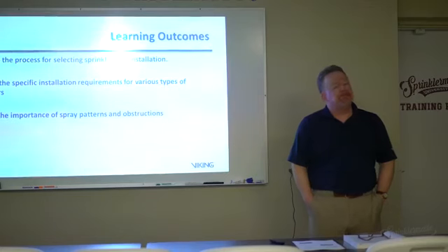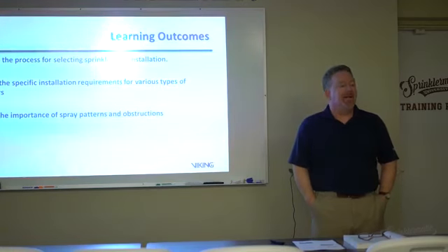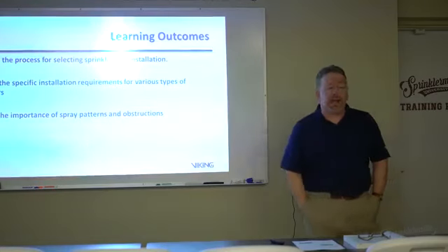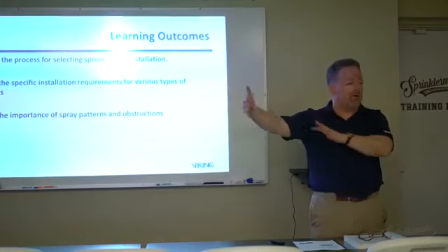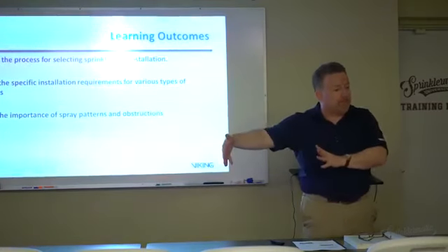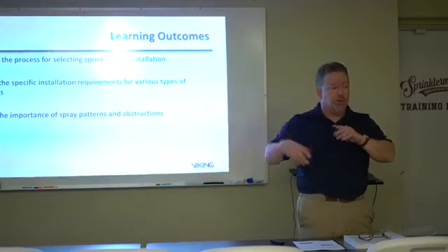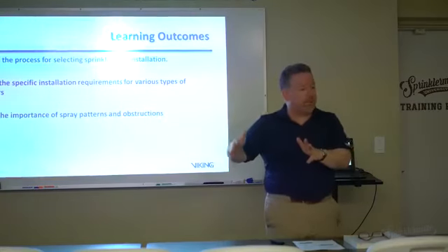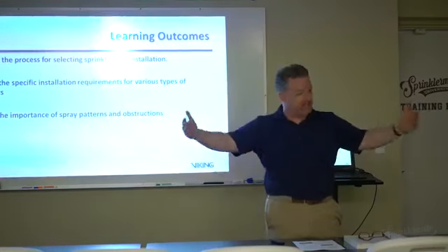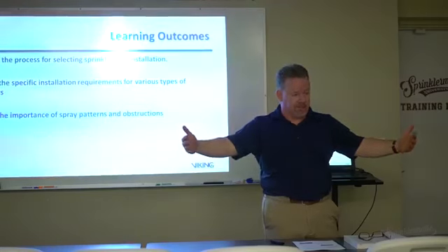If you wanted to change the hazard at a later time, is the piping adequate to go to, let's say, a medium hazard or a high hazard? Not a high hazard. Can you change out your sprinkler heads to meet a higher standard? You don't have to. Remember that in an ordinary hazard group 1 or an ordinary hazard group 2, you can use quick response in there as well. Right, but it wasn't built as a light hazard. So to your one answer, you don't have to change out the sprinklers from quick response simply because of a hazard classification change.